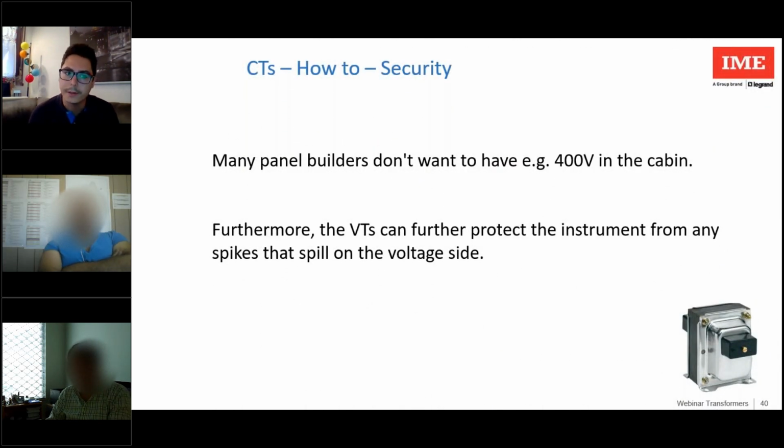For the security part, many panel builders don't want to have, for example, the 400 volt inside the cabin, inside the panel. Furthermore, the VTs can further protect the instrument from any other spike that spills on the voltage side.